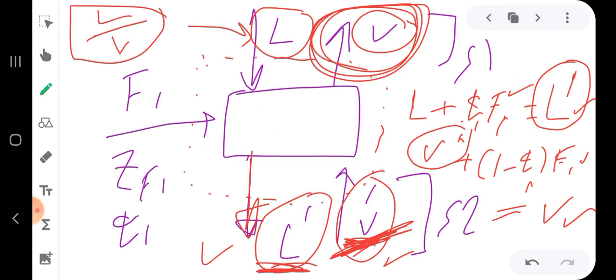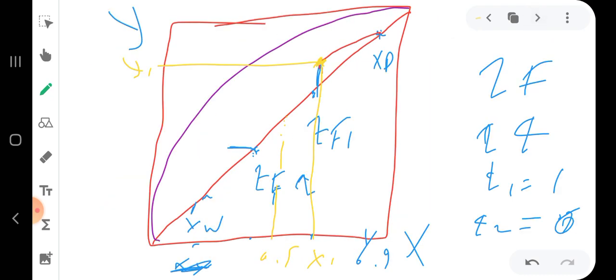So if you choose x2 to be 0.5, and then you find y2 using the equation, for example if you find y2 here, then what you have to do is connect these 2 points, the x1, y1 point and the x2, y2 point. You connect them until you reach the second Q line as it is extended.